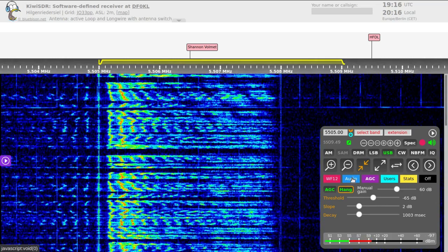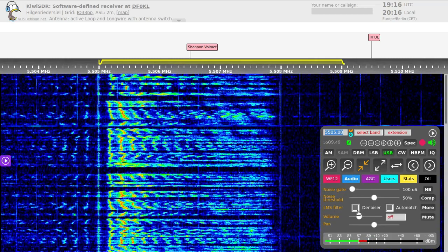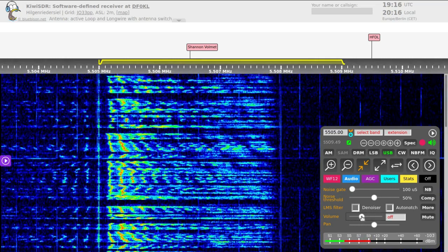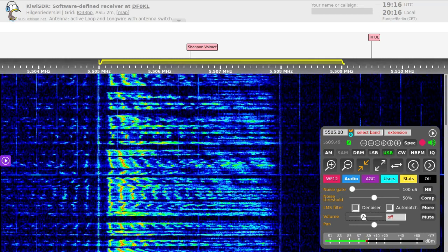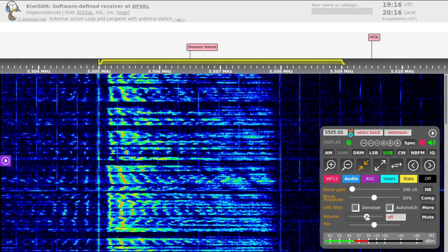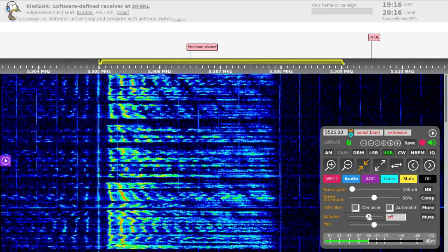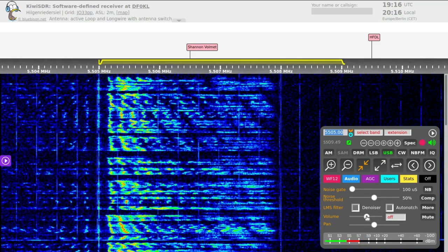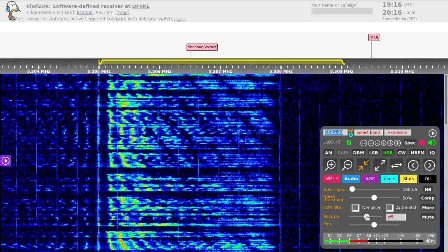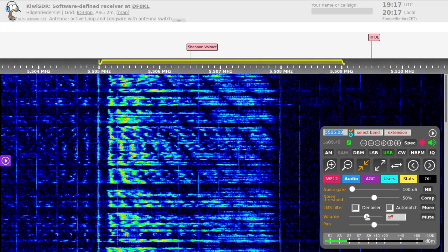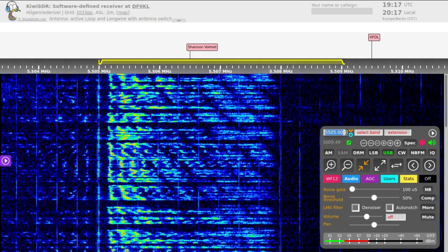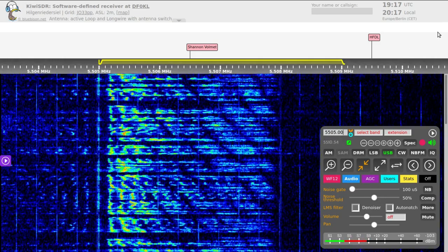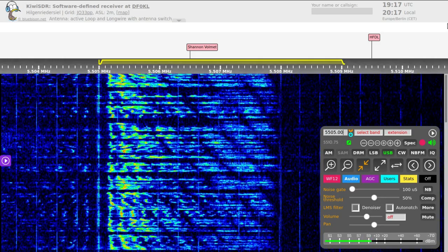Okay, let's talk about audio for a moment. After making the adjustments to the RF gain, or virtual RF gain in the SDR, it's then a fine time to make the last adjustments to the output audio level. You can see here we've brought the audio up slightly. That makes for a nice moderate audio level into the recorder.